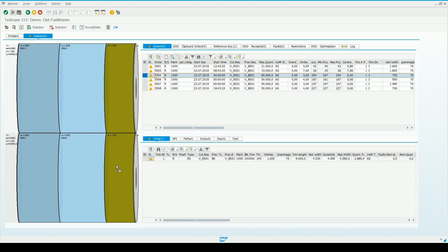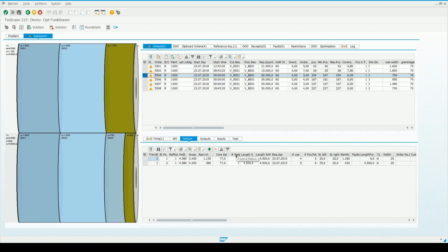So what you can do is go back here and add another solution, so we can compare later, and run an optimization including loss and yield to see what the best result is. So we'll run an optimization. It's calculating. If we look at solution number 1, you had a relatively small loss of 0.465%. Adding in yield, you can see it has slightly gone up to 0.514. However, the orders are completely fulfilled, so the coverage is 100%. You're covering that on yield.